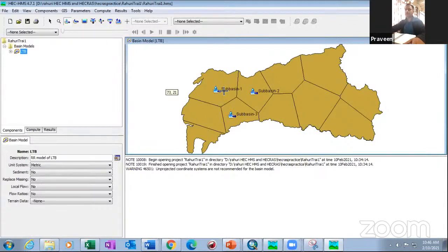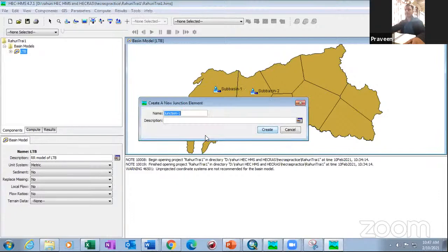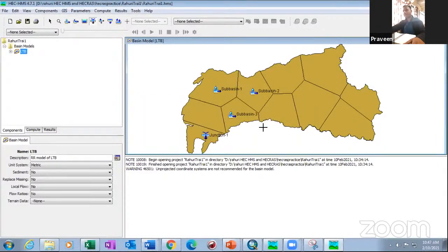Okay. So once you create these 3 subbasins, then what I want is this discharge has to come to somewhere, in the junction. Somewhere at the outlet point, right? So what I will create, I'll have one junction. These 3 subbasins are contributing at this point. So I'll just create one junction. Then how can I bring this discharge to this junction? For that, what I want, I should have...